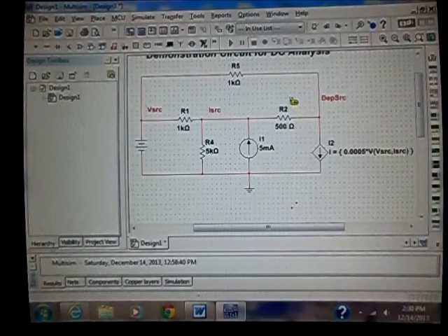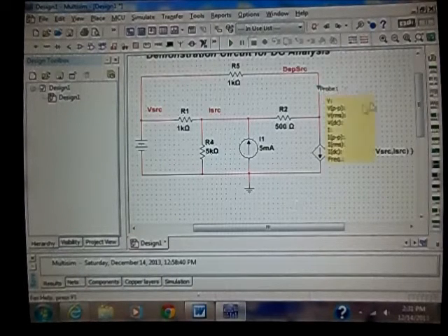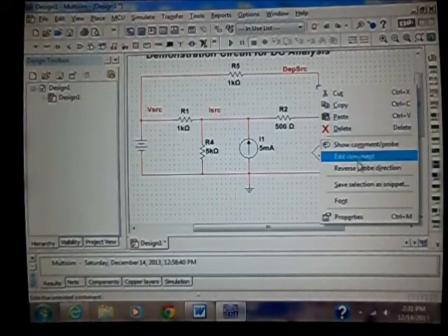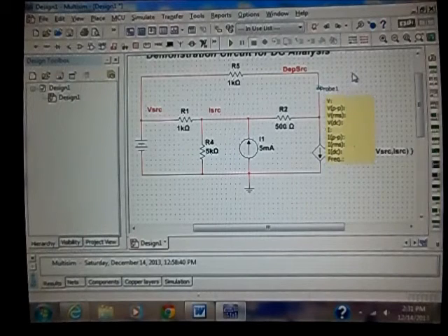And clicking on that, I bring up this little yellow thing. Let's say that we want to measure the current downward right here. So I bring the measurement probe close to that, and I get a little arrow pop up on the wire. Then left clicking deposits the measurement probe. Now that's going to measure the current downward as well as the node voltage here with respect to ground. If I want to turn that arrow around and measure the current the other direction, I'm going to right click on the arrow and click on Reverse Probe Direction. That turns the arrow around, as you can see.